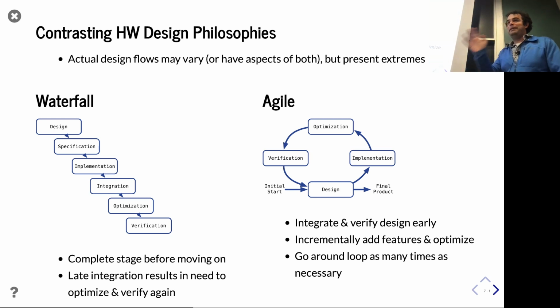Like, you've been in these academic tape outs. That's what they want, and you can't let them do that, right? Because it's not scalable, right? We've all done this. You take a design, you push it through a tool flow. You didn't do anything weird, and you have a DRC violation, right? Somehow your design is unmanufacturable because the tools didn't follow their own freaking rules, right? When you have that scenario, you need to use scripts to fix that. You do not let a human touch it. Because like I said, the scenario described.